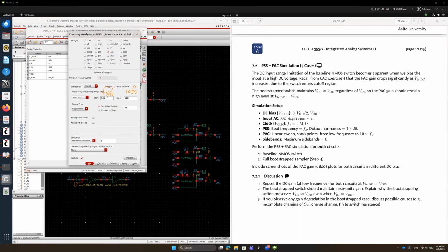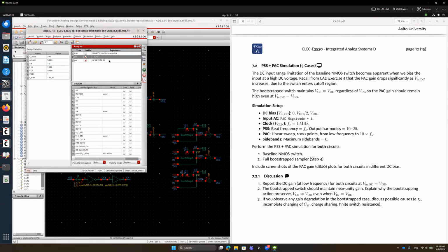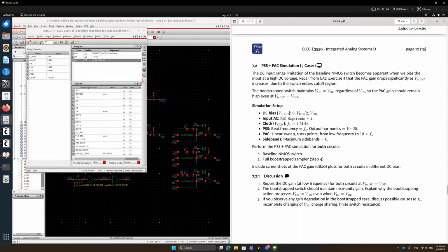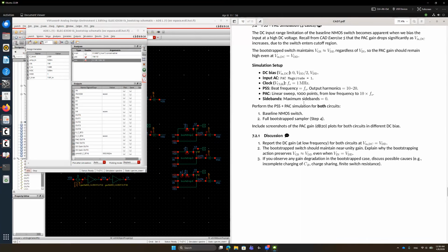And the number of points, I'll just stay with logarithmic 30 points. Of course, 1,000 points is recommended for very accurate simulation results, but for simulation time and the duration of this video, I will just run with 30 points only. And maximal side events, I set it as 0.